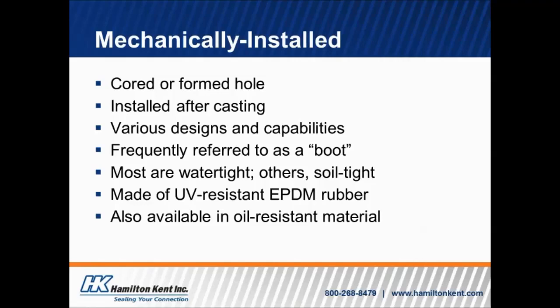They're usually made out of a UV-resistant EPDM rubber, and the reason for this is, number one, it has good physical properties, but number two, if they were installed at a precaster's facility and kept out in the plant for a few weeks, or if it goes to a job site and sits there for a few weeks, we're not worried about the deterioration of that rubber because of the UV. It has that UV resistance already, so no issues with ozone or UV rays.